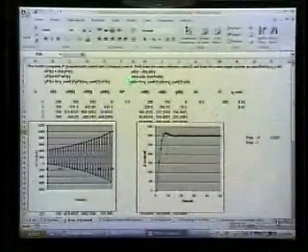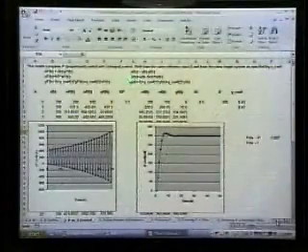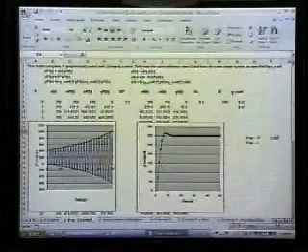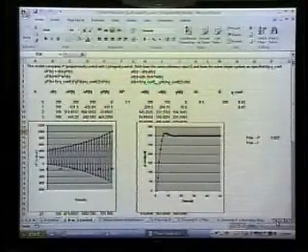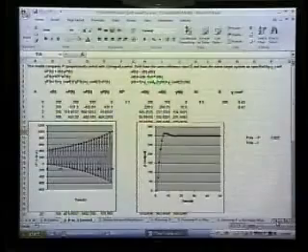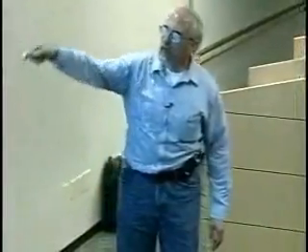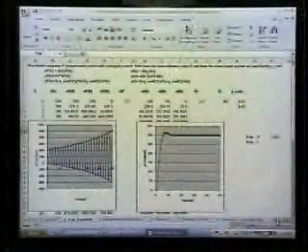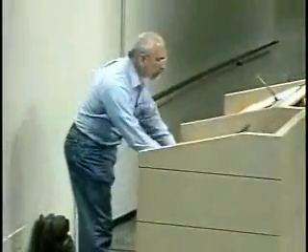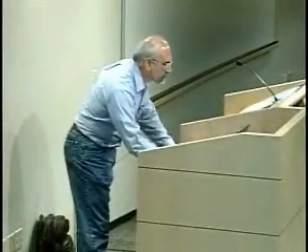So with the integral controller, we see UI is equal to the last U plus this increment, which is Ki, the integral control constant, times the error for the integral control times K. The systems are the same. So that makes sense? We just go through briefly what the calculations look like here.